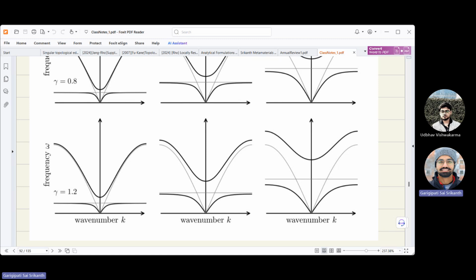So when you say you're increasing or decreasing coupling strength, you're basically messing with mass. And when you say that you are increasing the resonating frequency, you are sort of tuning the stiffness, right? If you keep the mass the same and keep stiffening the spring, you ultimately reach a fully rigid spring. The optical band, the band above, will keep going higher and higher, and it will disappear into infinity.